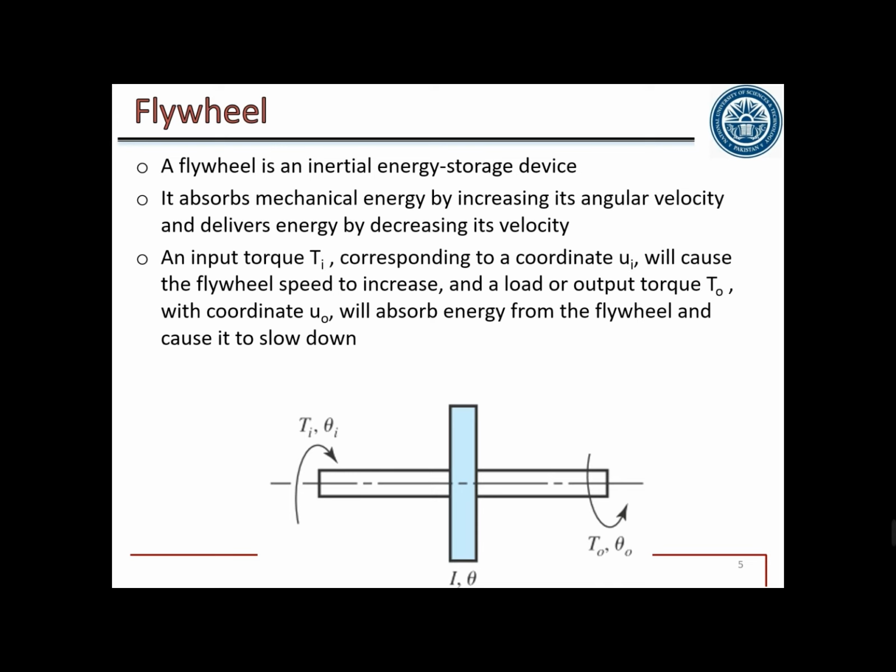Another function of the flywheel: if there is an engine in the car, and let's say you have 4 plugs, after each 90 degrees of rotation of the crankshaft, each plug provides a power stroke. So you have a power stroke here, here, here and here. If you make a graph on the horizontal scale, you have a power stroke here. For the remaining 90 degrees there is no power stroke, but suddenly after 90 degrees you have another power stroke. So the omega input from the engine will be discontinuous.